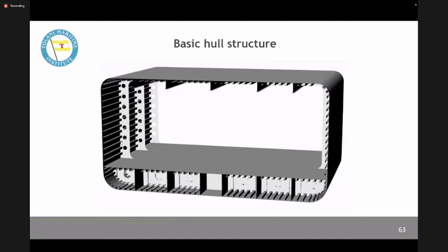Look here. If there is no hatch cover shown, it cannot be a bulk carrier, right? Yes, sir. So if no hatch cover, we cannot say it is a bulk carrier because how are they going to load it? Then it would be a general cargo ship.